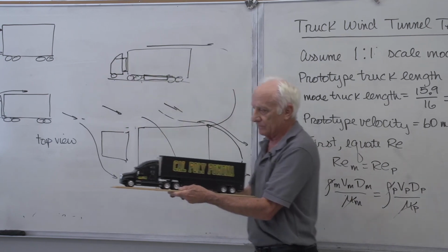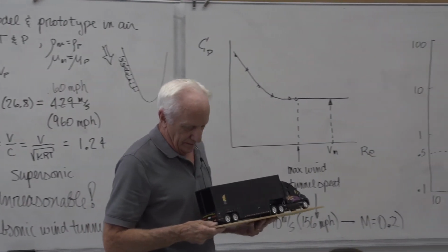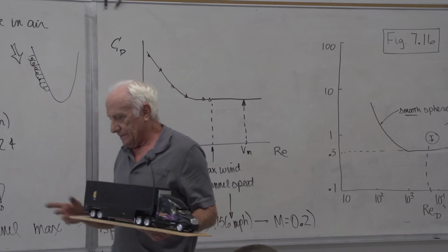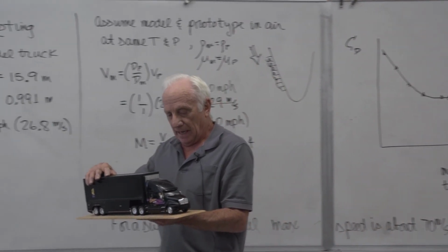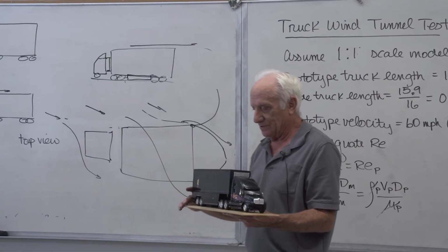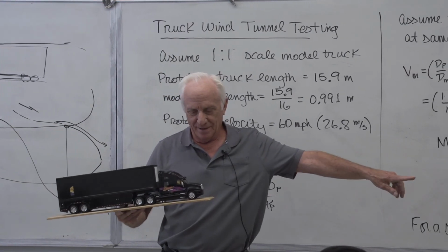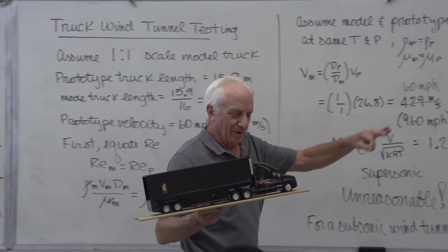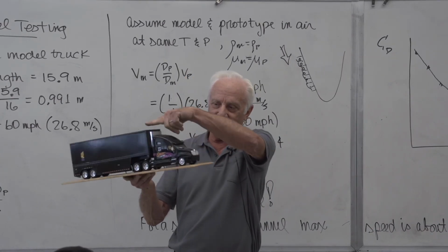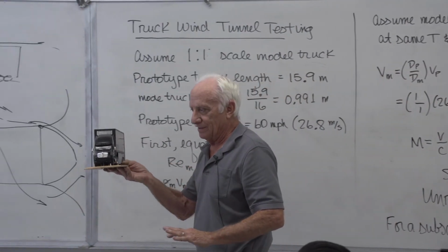Here's the cab fairing. And I told you there was a wind tunnel down in the fluids hydraulics lab. And these technology students built this thing. And then they put it in that wind tunnel. And they just wanted to see the smoke lines around here. So they, up here where the wind comes from, this way, they dropped oil onto a hot wire to create smoke. And they watched the smoke go across here and how the smoke patterns work, took pictures at various Reynolds numbers in there to see how that changed that.